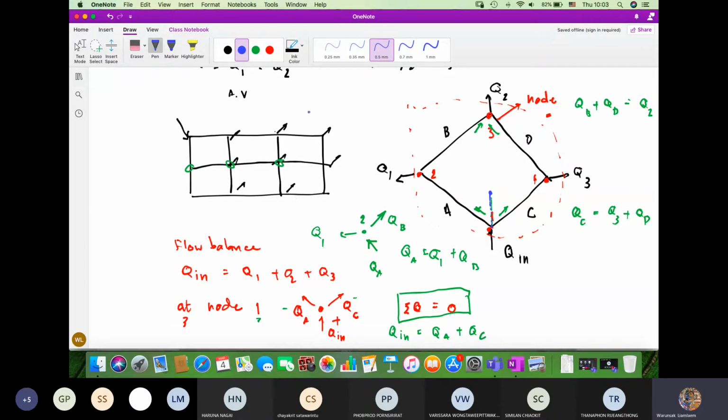Remember that when we talk about energies, it means that we talk about the three terms in combination. The energy due to the elevation, which we usually call the elevation head, plus the pressure head, plus the velocity head, V squared over 2g. So if you compare with the energy at node number 2, this must be equal to the energy at node number 2. So this is at node number 1, P2 divided by gamma plus V2 squared divided by 2g, and of course plus the head loss which occurs due to the flows along the pipe. Now we are considering the flows through pipe A.